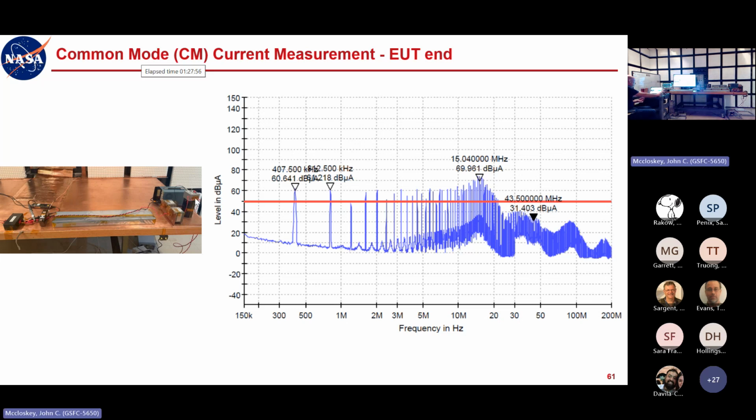I walked through at least some of the theory last week in my transmission lines session. If you want to watch the video, I go through the theory in rather painstaking detail, but the bottom line is that at a shorted termination, the current maximum is going to be at the short, which actually kind of makes sense, and then the math backs it up.